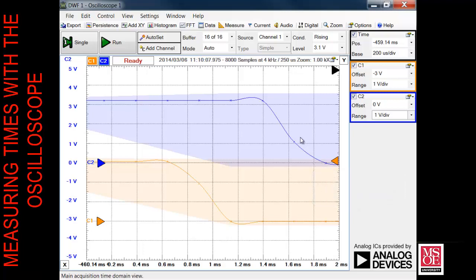So we're down in the millivolt range. So we can measure time across the horizontal and voltage across the vertical axis. Voltage is analog. We need to do the translation to realize that anything that is around 3 volts is a logic high. Anything around 0 volts is a logic low.